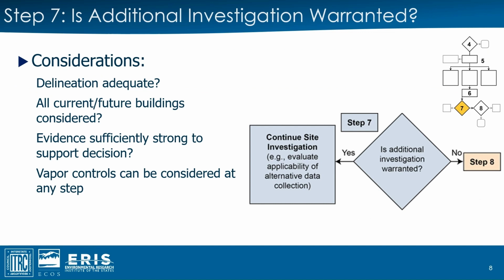The last steps in the process are simply to determine whether the conceptual site model is sufficient to either eliminate the pathway or whether additional data are needed. Actual cases of petroleum vapor intrusion are generally rare and limited to ones associated with shallow LNAPL sources where there's limited oxygen available between the vapor source and building foundation for aerobic biodegradation to occur. These are usually sites where building occupants are complaining of petroleum odors.